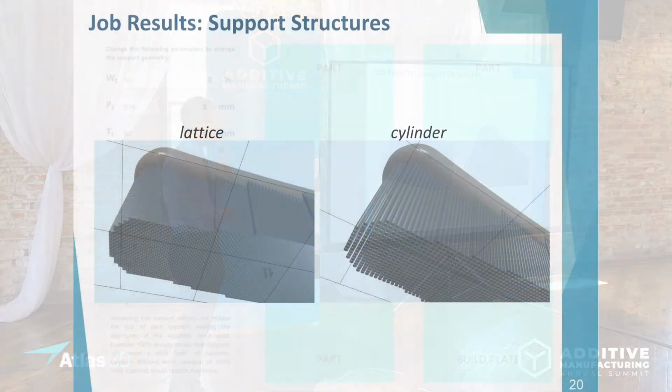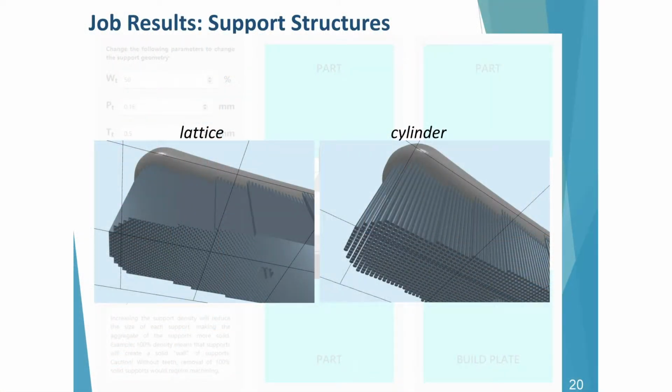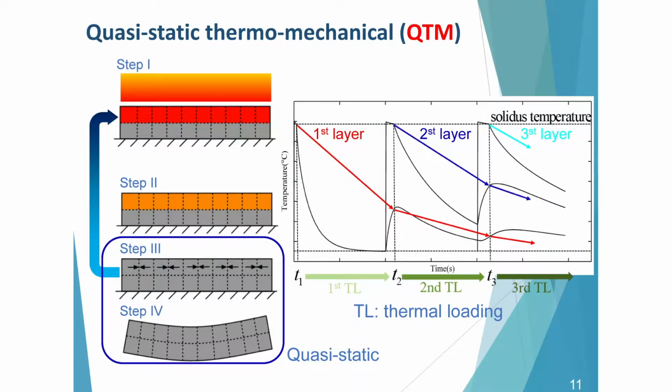And this is the comparison between the TCN method and the finite element method. For this horizontal part, it takes about 2 minutes for TCN and about 14 hours for finite element. For the vertical part, 18 minutes for TCN and 41 hours for finite element. We only sacrificed less than 15% accuracy, but we achieve about 2 orders of magnitude speedup.